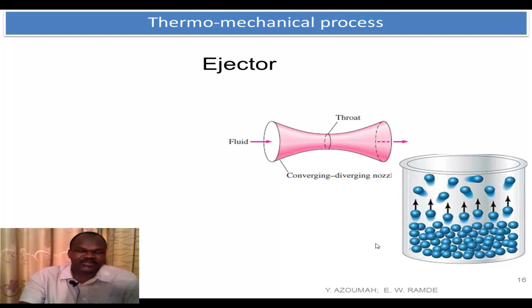And that is used in the evaporator side of any air conditioning system or any refrigeration system. You have the compressor sucking the vapor from the evaporator, and more liquid is coming to evaporate, and in doing so, is picking up the heat from the evaporator, and that's creating cooling. And this is the same way here.